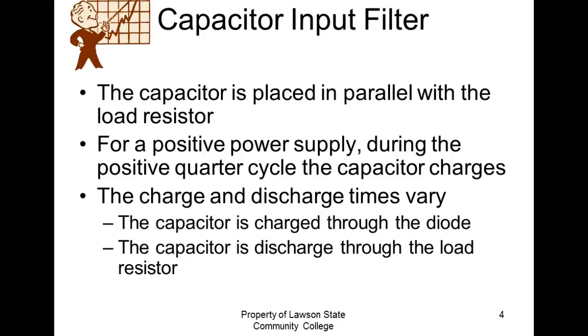On a bridge, you just hook it up the way you want it, because the ground is established on the output of the diodes, or the common. On a half wave and a full wave center tap, the common is established at the transformer. Since on a bridge the common is established on the other side of the bridge, it depends on how you hook it up, right?